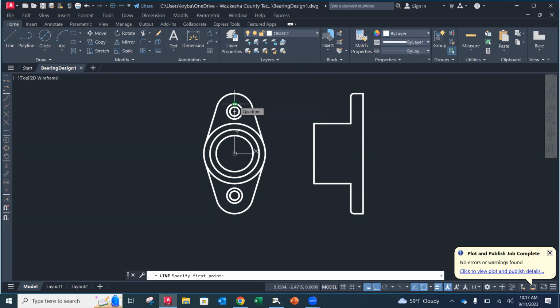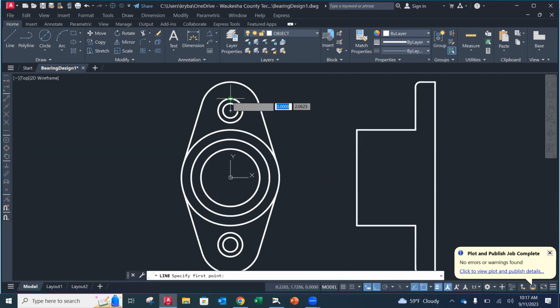So I'm gonna go to the inside hole first. Okay, I'm gonna click on this because I want to activate that. Again, that's because my quadrant is on. And as I move over here, once I get to the part, it's gonna find an intersection. That's what that X is. I'm gonna click, and then it's gonna go perpendicular and click, right?